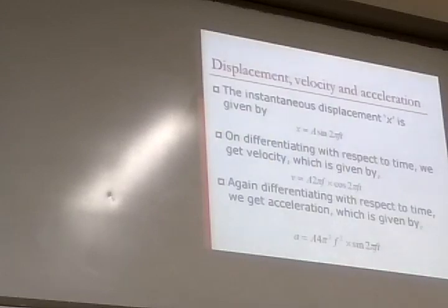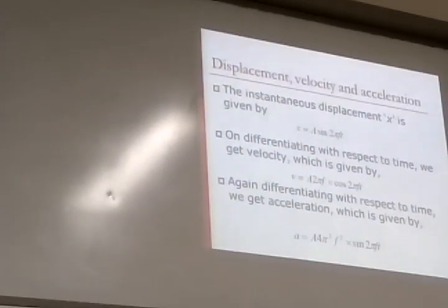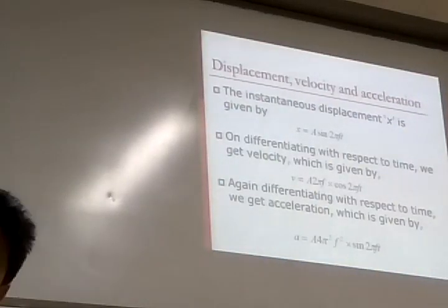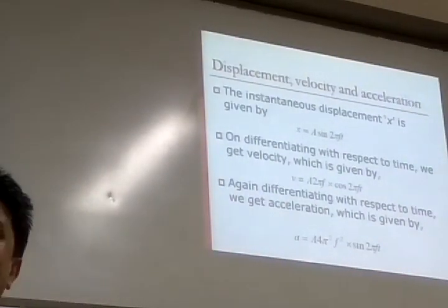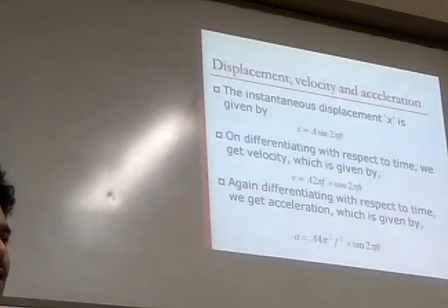Very minute things I am talking about. It is very difficult to measure very minute vibration. If the amplitude is big, it's easy to measure. In that way, velocity is easy. Also, as the frequency goes up, the amplitude of higher frequency signals goes up. In certain applications, it is advantageous. In certain applications, it is disadvantageous. So you have to look at what is my application. Accordingly, I have to choose which parameter.